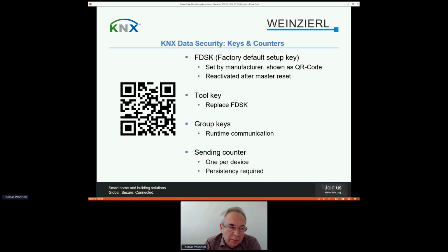Nevertheless, somebody may know this key, maybe somebody took a photo of the device, of the box where you can find the FDSK. That's why the FDSK is only active at the beginning, and ETS replaces the FDSK by a so-called tool key. Although the tool key, we do not only have one for the installation, we have one for each device.